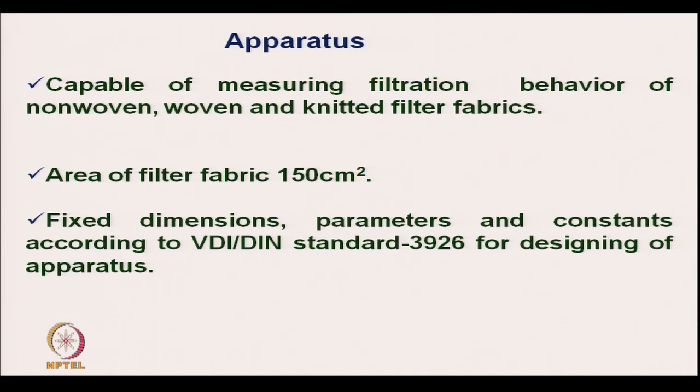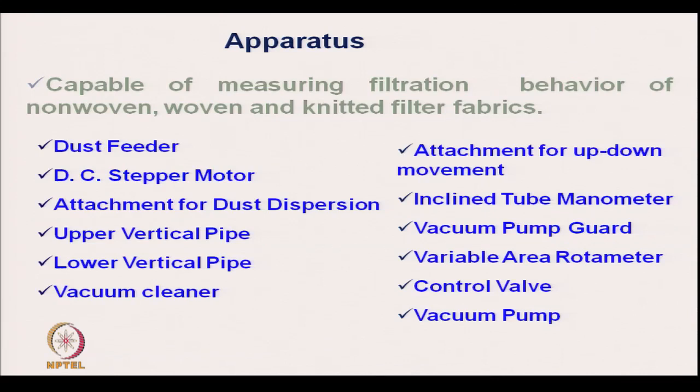The area of filter fabric is 150 square centimeter. We can also change it. It has fixed dimensions, parameters and constants according to VDI DIN standard 3926 for designing the apparatus. So, this instrument follows this standard.